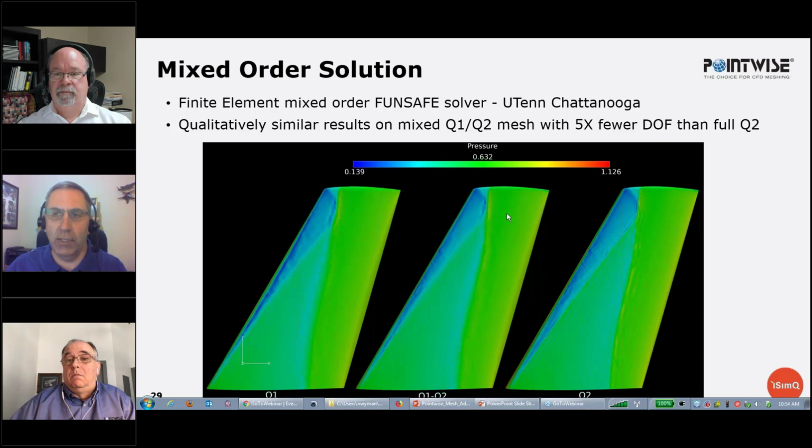And the reason for that is because meshing is a binary choice. Often, do I add a point or do I not add a point? That's a binary choice. You can get into some oscillation between these cases where it adds a point, then the next iteration takes it out, and vice versa. By keeping 2 point clouds around, we saw that largely eliminated. And you would do the same thing for a transient case. If you have a transient case, you would need to monitor the period of the transient, and you would want to keep around that many point clouds.